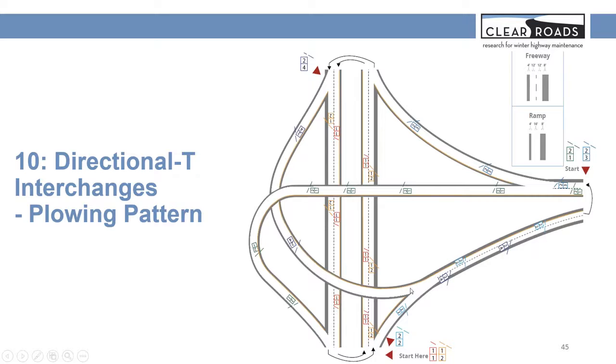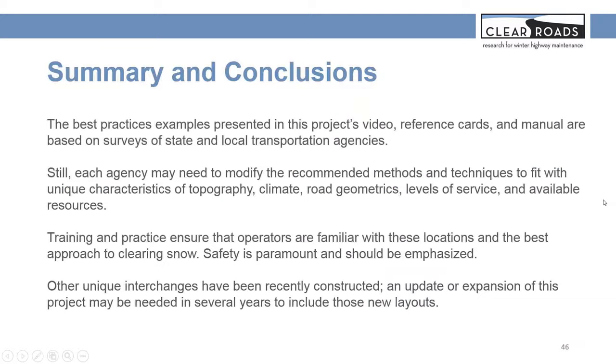After the curve ends on the flat part, the truck will shift to the right-hand side and extend the right wing and the front plow push to the right to clear the right lane and the right shoulder, and continue to merge onto the minor road, and then complete all the passes.